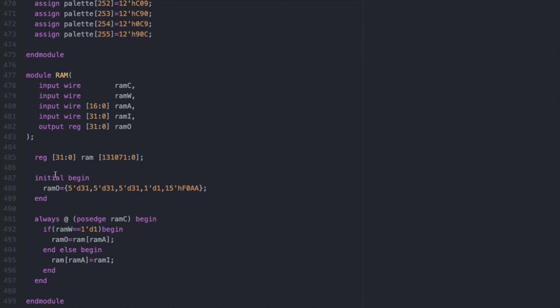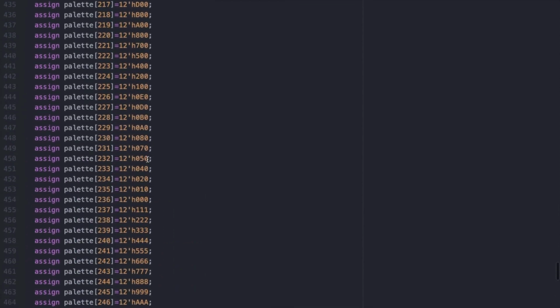And here we initialize it. Every time you use a reg, you must initialize it. Otherwise, it won't work. It'll have X. It won't have Z. It won't have a 0. It won't have a 1 anywhere in the bits. It'll have an X. I won't know. Of course, this is too many regs to fix right away. So I have that initialization procedure.